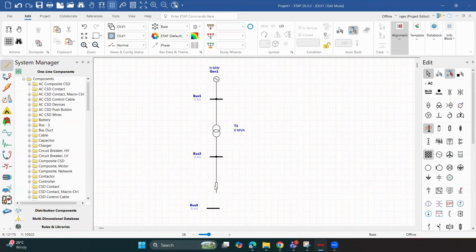Or, if you want to recall your college theory, the single machine infinite bus system, you can also put one more line, a double circuit line. But I have not given any parameters or values. I have not given voltage, I have not given powers. If I run, nothing will work, but at least I have created a skeleton single line diagram. This skeleton single line diagram helps two things. There is something called check circuit continuity.